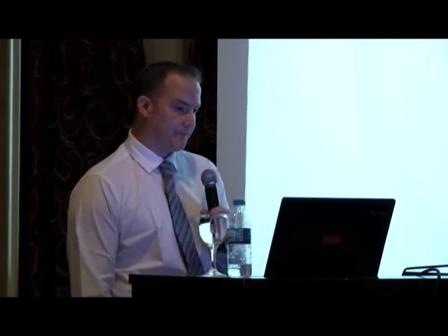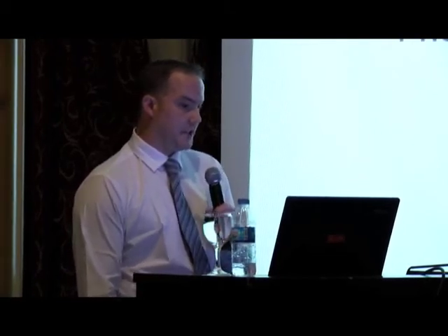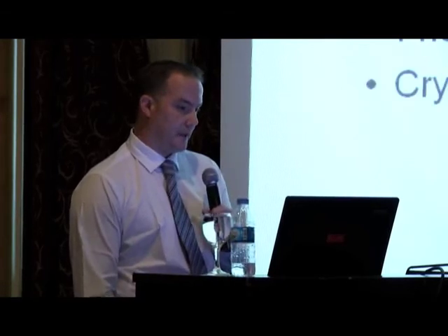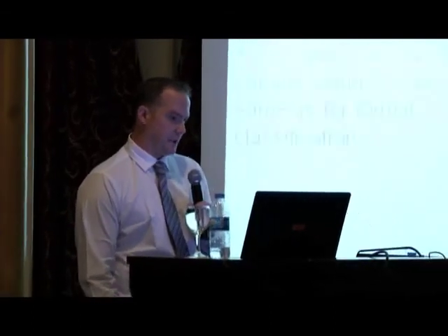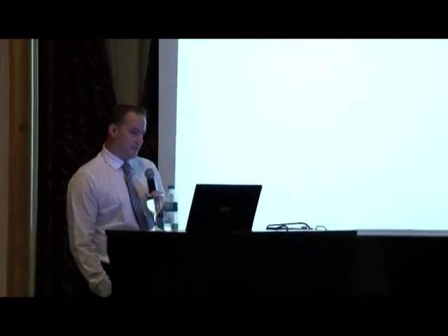So basically, facility monitoring systems can monitor airborne particles, non-viable and viable. Previously we talked about non-viable with that. Room pressures and airflow. You can also measure temperature and humidity of rooms. And you can also monitor lots of equipment, such as fridges, freezers, and incubators. And within that, as well as monitoring temperature, you can monitor carbon dioxide and oxygen levels. I'm going to skip through this section because I think we've pretty much covered it on previous presentations.